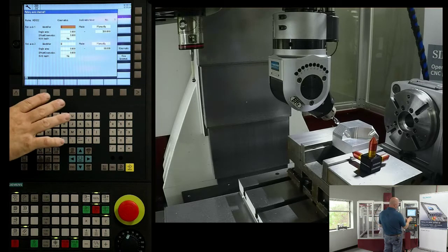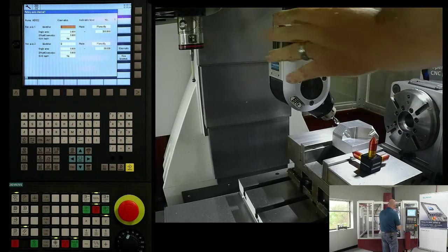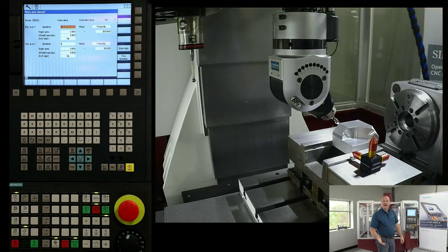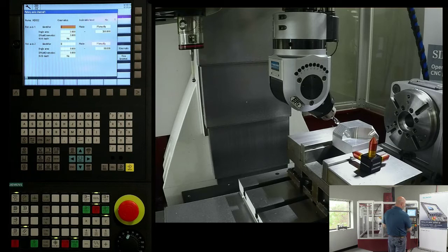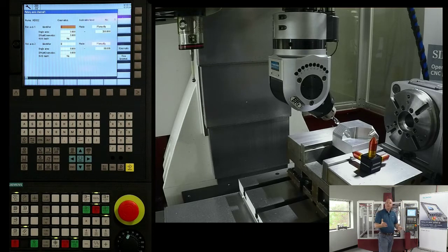So what I did in mine is I called the rotary that spins around my spindle the C axis, because that's an industry standard for that type of physical kinematic axis, right? That would be the ISO standard. Any rotary that revolves around my spindle is defined as the C axis. And then we have the B-axis. The B-axis, the ISO standard would be, that's the axis that would rotate about the Y. So I just use those two values.